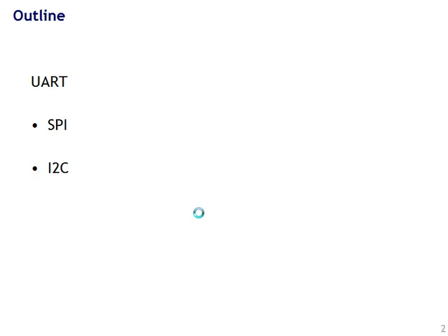The slave will be your slave chip. The master will probably be something like your microcontroller. The I2C, or sometimes called I-squared-C, is an interface which gives you a two-wire serial interface, instead of SPI, which requires a clock and gives you a four-wire serial interface.